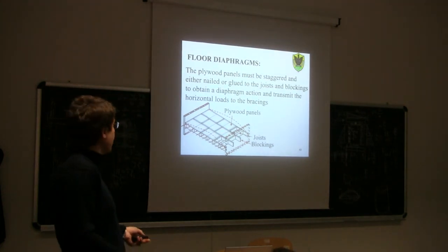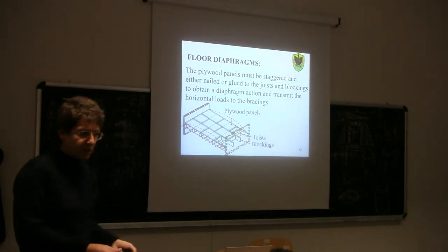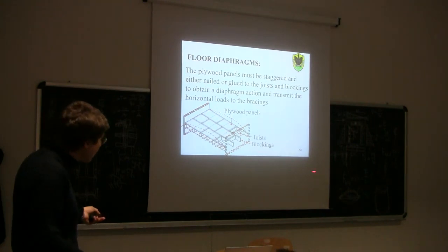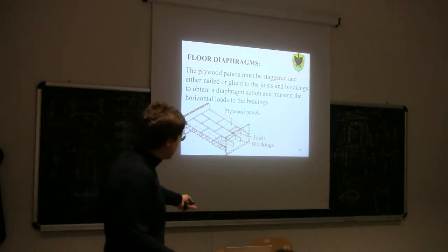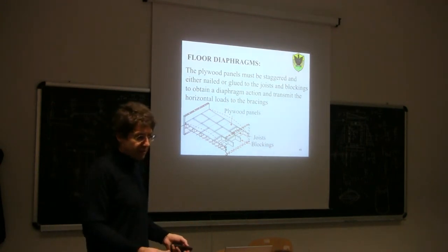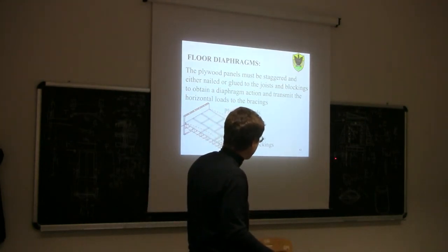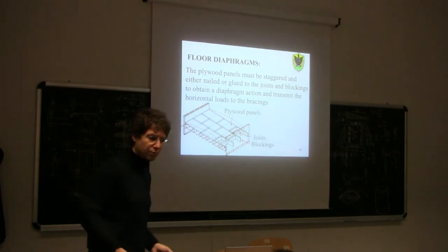And then the question was about the nails. Are they going to be significantly stressed by the vertical load or not? This was a question. No. Vertical load, no, unless we consider composite action. But the composite action done in this way is quite negligible. In fact, if you want to achieve a composite action, you need to have a glued connection or to have a timber-concrete composite structure.